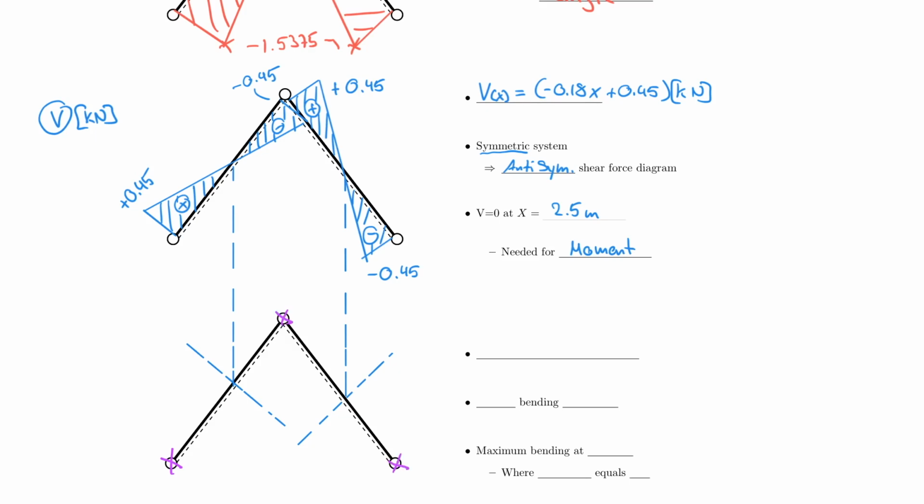And remember that snow is also attracted by gravity, just like the self-weight. Therefore, I don't have to change my logic of the beam smiling or frowning. In fact, it's smiling. Therefore, I must end up with a maximum in the middle and my moments are positive, positive, and positive right there.